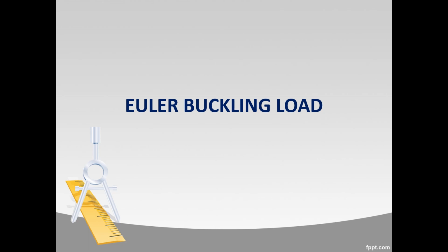Before starting today's lecture, what we discussed in our previous lecture was that when a long column is subjected to some axial compressive load, a phenomenon occurs in it which is known as buckling, and buckling means the lateral deflection of those columns. Suppose this is a column, and a certain axial compressive load P is acting on it. This axial compressive load causes axial compressive stresses in the column, given by the load divided by the area of the column.